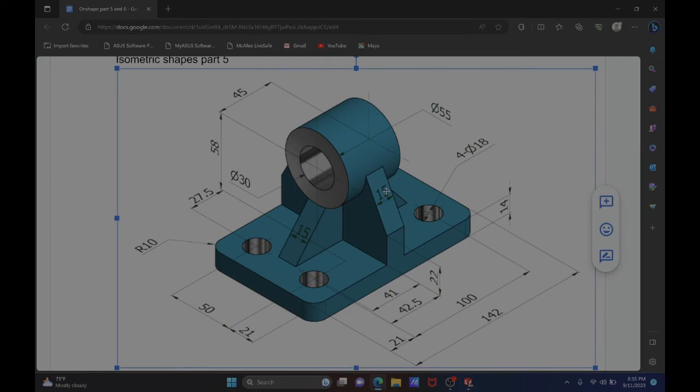And I'm going to teach you something new in this case, which is that I can extrude in two directions. Okay. So my first direction, I need to extrude by 15. Okay. 15, and this 15 is going to give me 30. And then I need to extrude by another 15 to give me my 45. Okay. Again, remember this has to be symmetrical. So 15, and I need to have another 15 in this case, which makes 30, and then this 15 in the middle will give me 45.